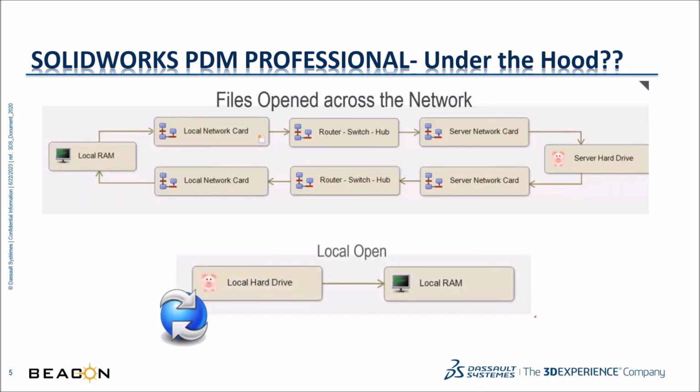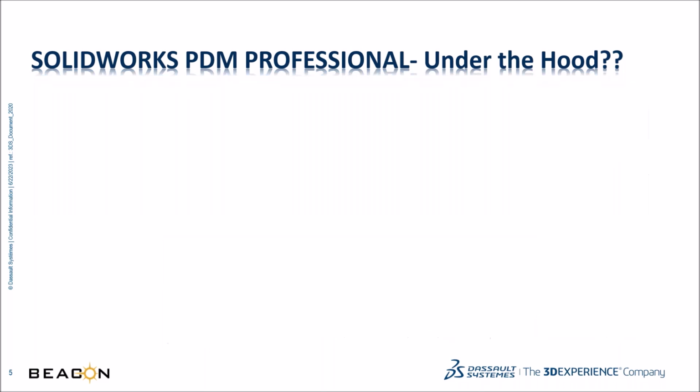In PDM, when you open a file on your local system, the file comes to your local cache. That means you are working locally on your system. So all those processes get eliminated, and the file directly comes to your local cache. You can work on your local cache and push those files towards the server. So you will get a performance gain using SolidWorks PDM.